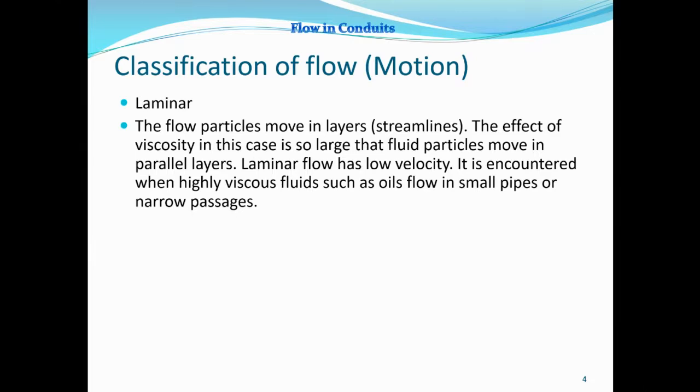Laminar flow usually has low velocity. That is why the fluid particles can move in layers without mixing, and it is encountered when highly viscous fluids such as oils flow in small pipes or narrow passages. Normally it is applicable when you have a highly viscous fluid like honey, like milk, which is thick. When the viscosity is high, it moves slowly and in clearly defined layers or streamlines, without mixing.